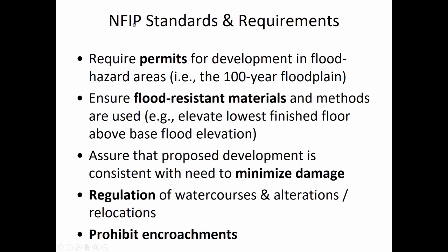The National Flood Insurance Program is set to require permits for development in flood hazard areas. In practice, there's a lot of development that happens that's unlicensed and unregulated. On my drive home, I go through a pretty rural area where a guy has set out a sign that says fill needed. Anytime there's construction, or even when the highway department dumps their leftover asphalt in his yard, he just pushes it into the creek because he wants more space to park cars. Everybody just wants a bigger yard. I ought to take pictures because that'd be a great illustration. I'm sure you've seen it. People dump soil into the creek, and now they've got more flat land. But the problem is that it reduces the flow cross-sectional area, and it pushes the water depths higher.